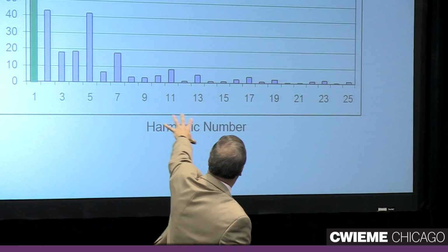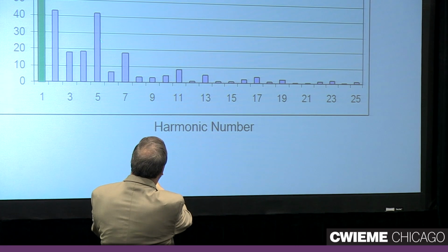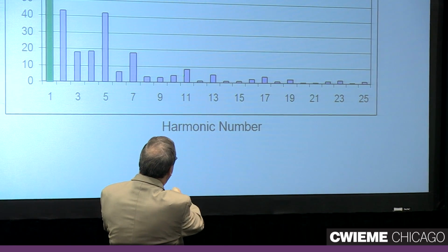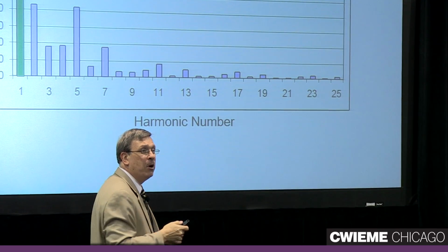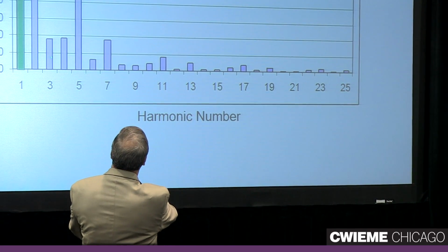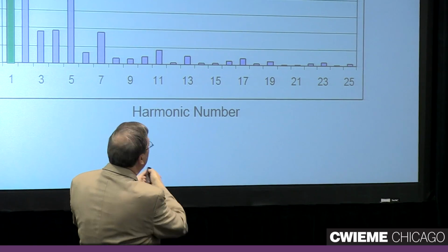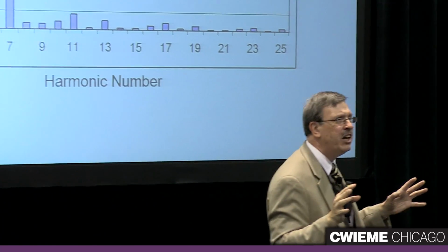And when you take a look at the spectrum, you can see the fingerprint of that 3-phase with that 5th and 7th, 11th and 13th, 17th and 19th. You see that there, but you also see some third harmonics. You also see some second harmonics. So usually, if there's even harmonics, that means there's a problem someplace. You really don't want to see even harmonics in your system.